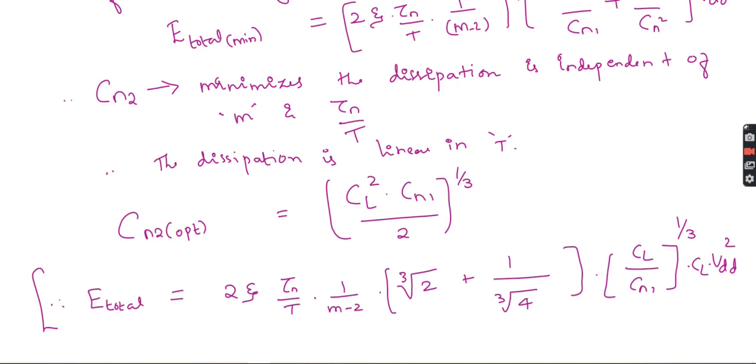We can even compare with the conventional buffer, just like you can compare the dissipations of the adiabatic buffer with the conventional one, for different speeds and different voltage swings. If you want to drive the input and the load of a conventional buffer with mobility scaled devices, giving the same total input capacitance for the transmission gate, that will cause a dissipation.